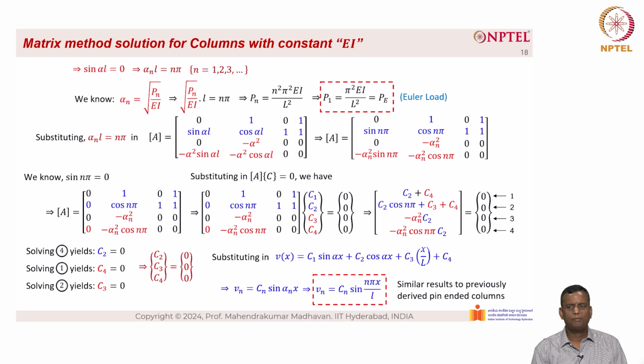So with this one, we have established that whether we solve the problem using matrix method or if we solve the problem using partial differential equation, we get the same result. Having established a benchmark using this matrix method, we can solve our problems with variable boundary conditions that are represented by linear spring as well as rotational spring.